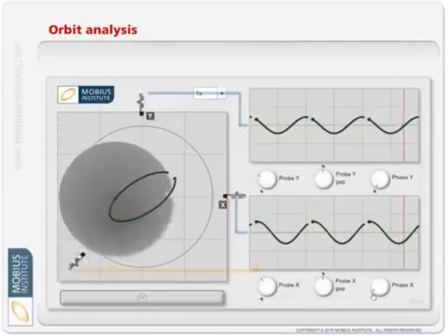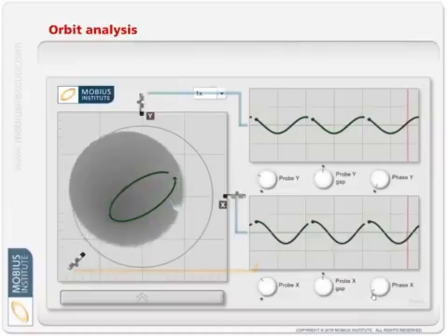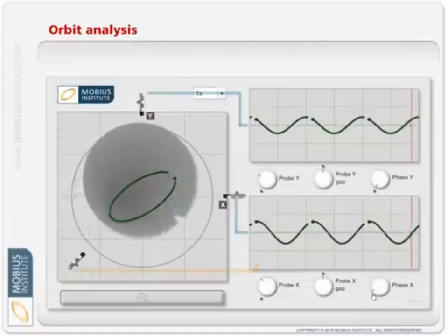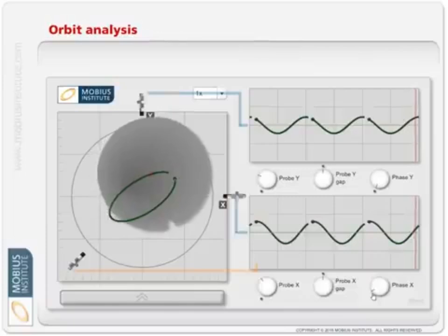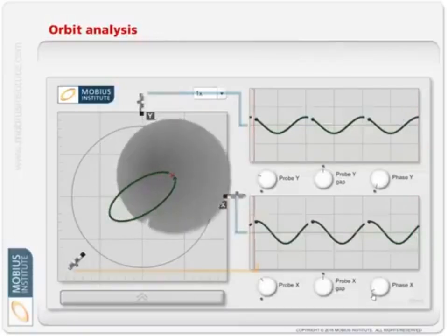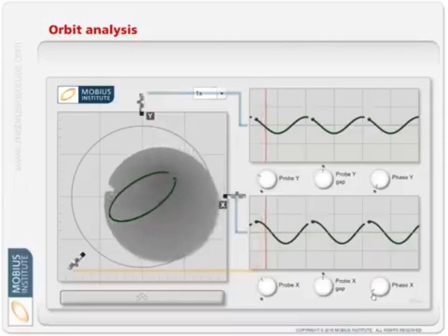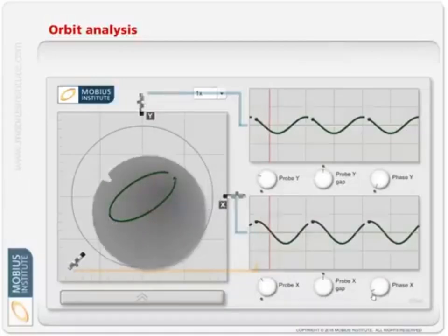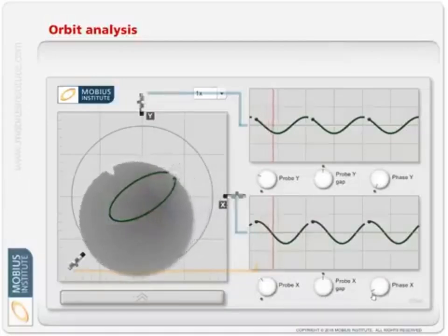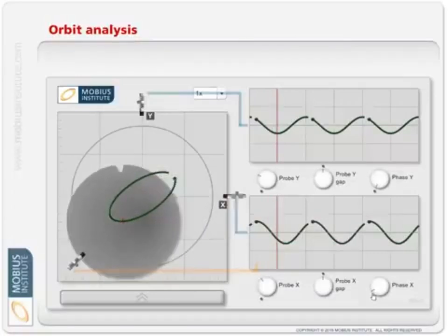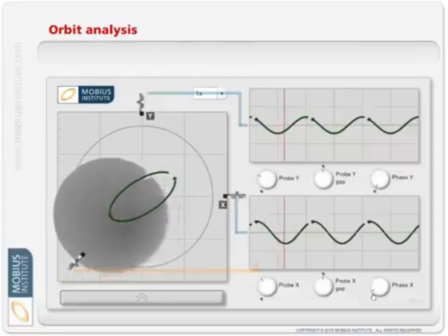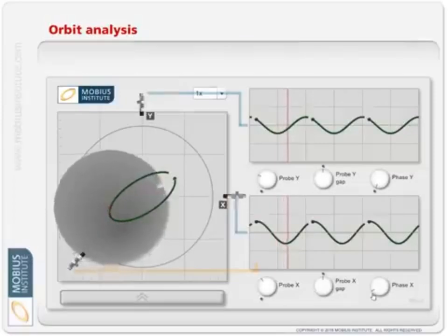Anyway, this is just to open your eyes to all the sorts of measurements we can take depending upon the type of machine and what it is we're trying to learn. So rather than looking at just a very simple overall level vibration, which gives us a very crude idea of how the vibration is changing, the spectrum, the time waveform, phase, and if appropriate, the orbit measurement really helps us to understand what's happening inside the machine. It puts us back in control.